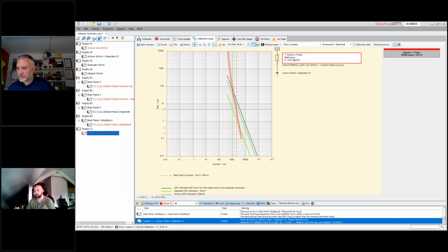It's when you get into much larger installations where you're trying to supply much larger power, maybe 900 amps plus to another location, and particularly in ground where you have to use the armor as a protective conductor. If you're doing it above ground, on spray work and the like, you don't have to use the armor as a protective conductor.